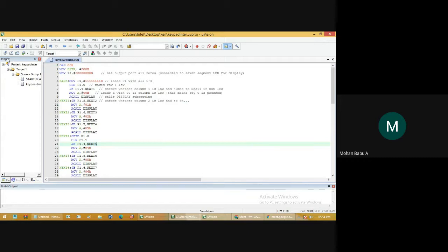And then choose translate. This is the first option on the left side top. Click the translate. This will show zero warning. Then go for build, the next icon. Choose build. This is showing zero errors. Then go for rebuild. If you click rebuild, this will show zero errors.